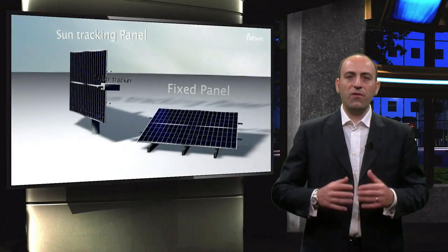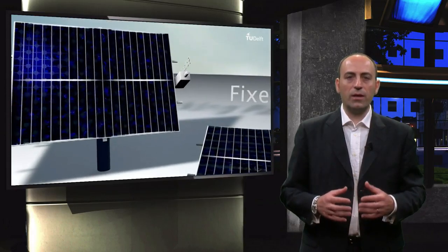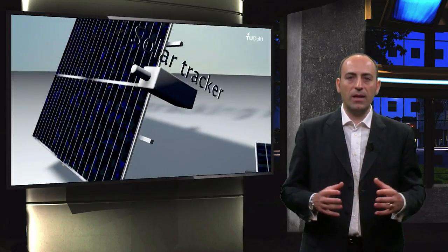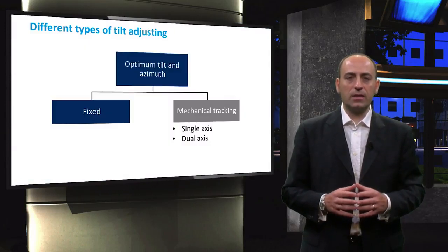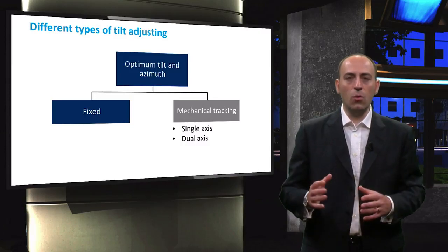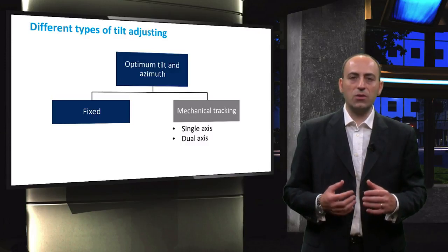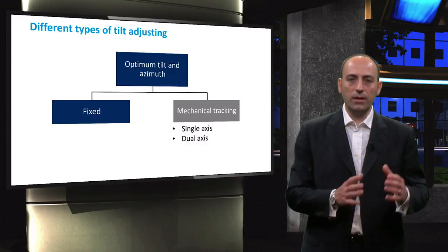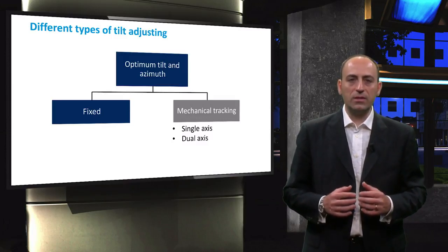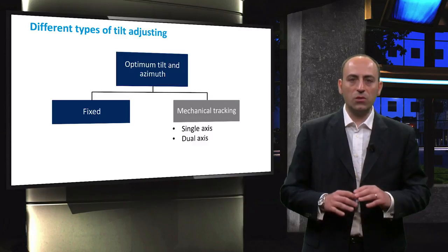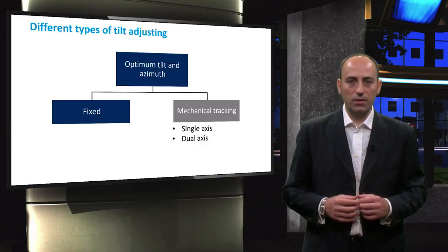By now, we have seen fixed and adjustable panel mounting configurations. Now we focus on the final method, which can be found in large PV plants and photovoltaic concentrator systems. The mechanical tracking systems can be divided into single-axis and dual-axis systems. For flat panel photovoltaic systems, trackers are used to minimize the angle of incidence between the incident sunlight and the PV panel. The primary benefit of a tracking system is therefore that the solar panel is continually tilted at an optimal angle, thereby maximizing the incident irradiance.